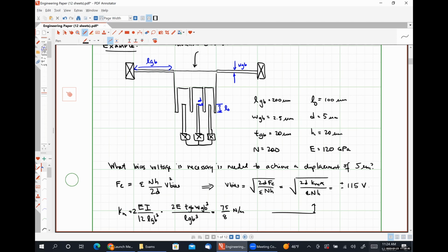So for the first few devices that were developed using this scheme, the capacitive tuning range was somewhere around 300%, which is roughly twice as large as we saw for gapped tuned devices. After multiple iterations, that research group was able to get a capacitive tuning range of over 700% with actuation voltages of less than 100 volts DC.